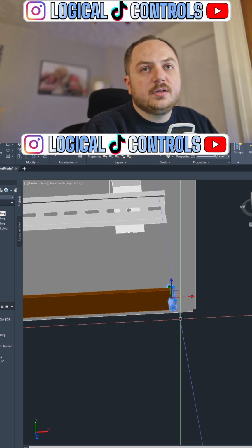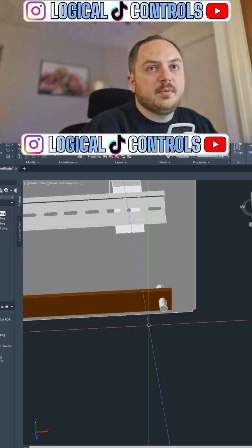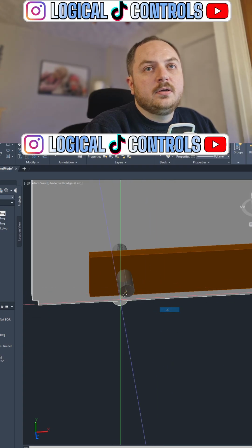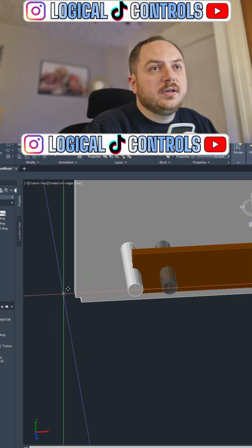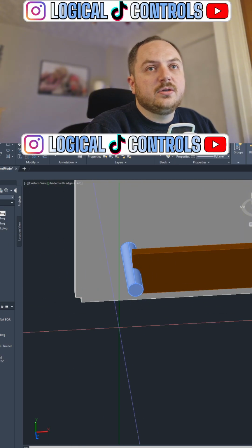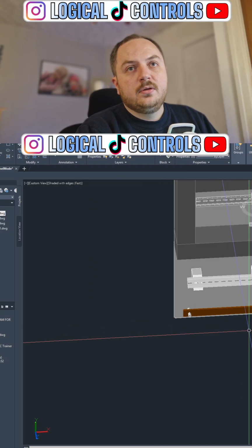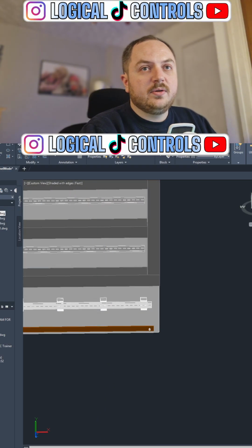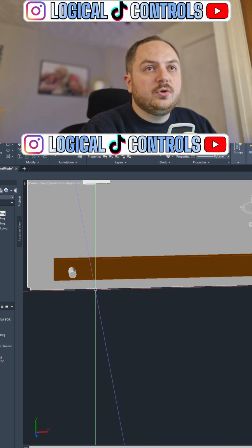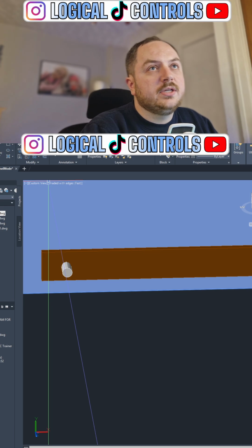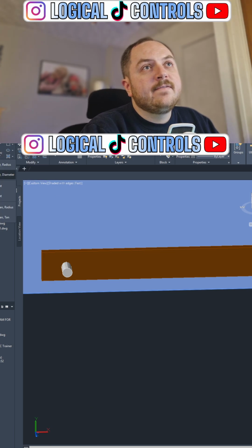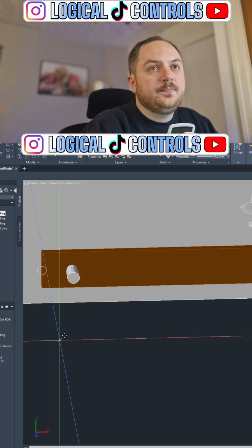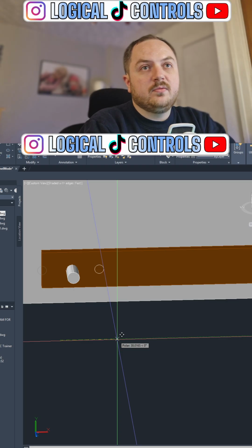There we go. So that's that one there. Bring that in by... I can't remember how much we brought the other one in by. Did we do anything? Just for the sake of completeness, I'll put an actual dimension against it. So let's bring it in by 20mm. I did the other one by 10. So let's do another 10. So there's 20mm each side. And you would normally punch a whole boatload of holes in it as well. So let's do that. Let's do diameter. Let's make the hole 6mm. They want to start about 50 in.